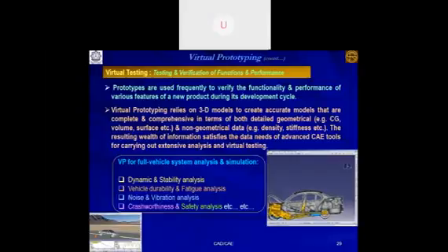And obviously, if you carry out the crashworthiness test physically, by changing parameters like speed and obstacle behavior or obstacle property, then let us say you have to carry out 80 crashworthiness tests. Each crashworthiness test will damage the car. That means you cannot use the same car for the second test. So you need 80 cars, and it is destructive testing. You have to throw it away, and based on the result you get, you change the design.